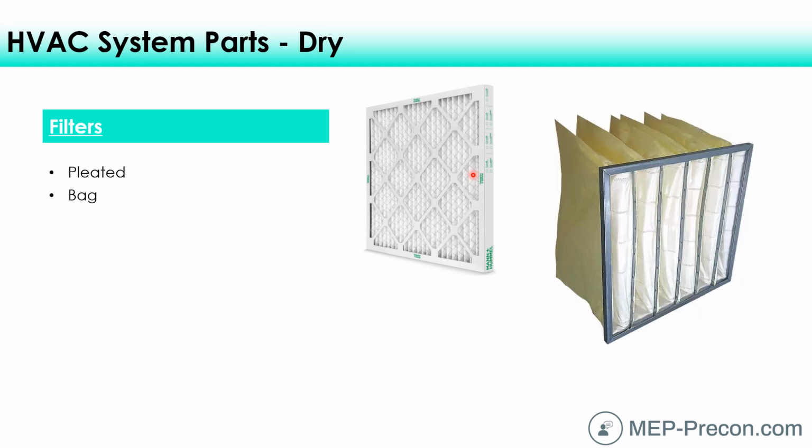Then there's a bag filter, and these are meant to contain a little bit more of the particulates and not change it out so often. They're a little bit more expensive, but they hold more dust and particles and so forth, and you don't have the maintenance cost to change them out so often.